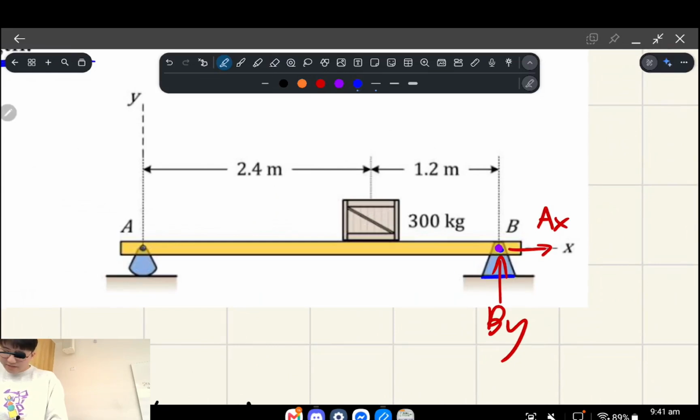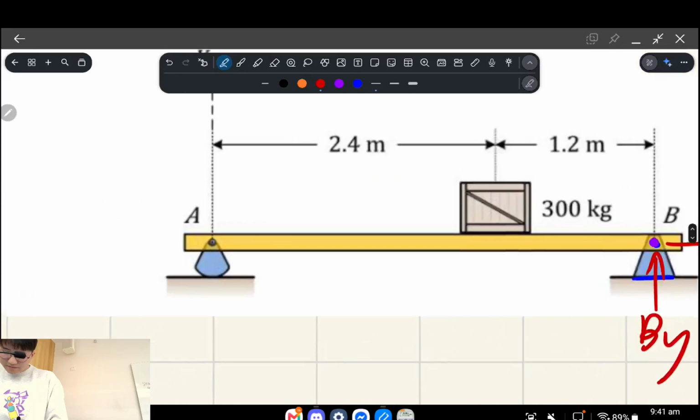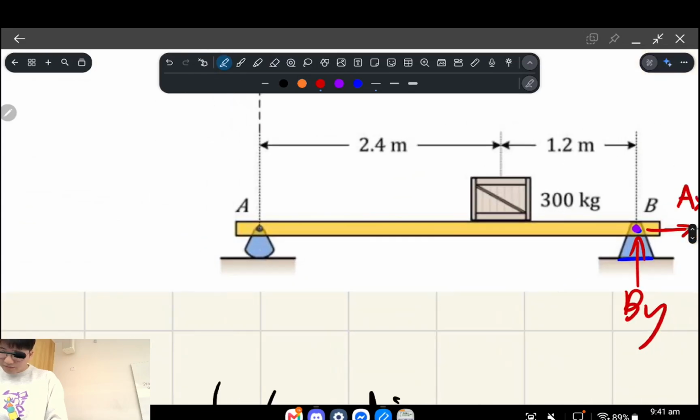However, this support on the left, right, is, I guess, more of a rocker support. So it doesn't quite look like, I'm just going to draw it on. It doesn't quite look like the roller that I was talking about before, but the thing is, it doesn't actually really matter because they mathematically behave the same. All right, a rocker and a roller effectively behave the same, and the reason is because a rocker will resist the